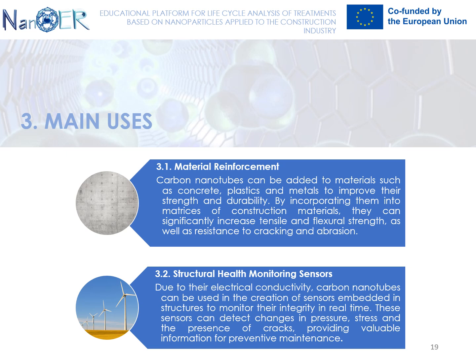CNTs are by nature excellent heat conductors, so they can dissipate heat from the concrete surface more quickly and protect it from thermal damage. Concrete durability can also be improved by the presence of CNTs in the cement matrix. CNTs prevent the corrosion of the cement and make it resistant to chemical attacks, such as the penetration of chloride ions, due to their excellent chemical stability. These facts lead to the increase of the service life of this structural material.